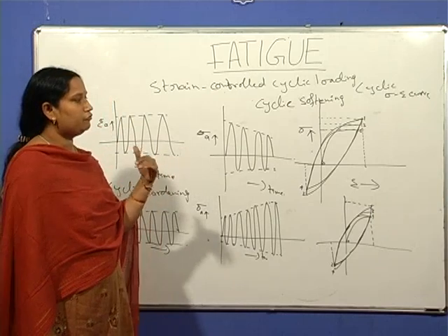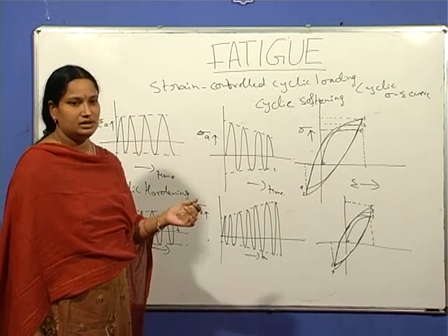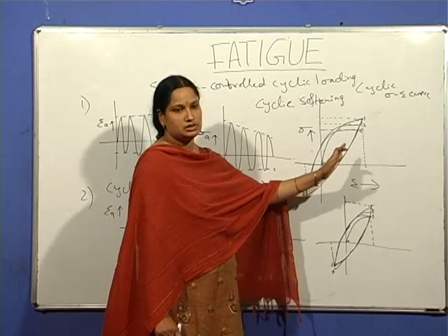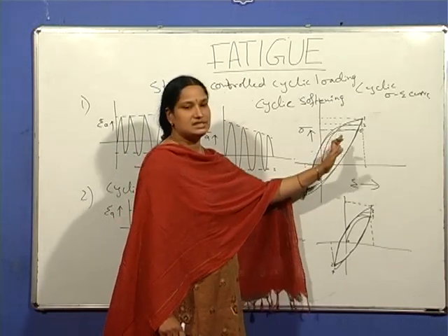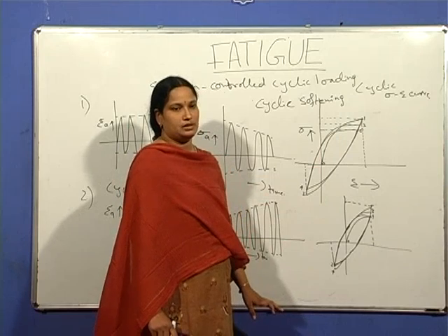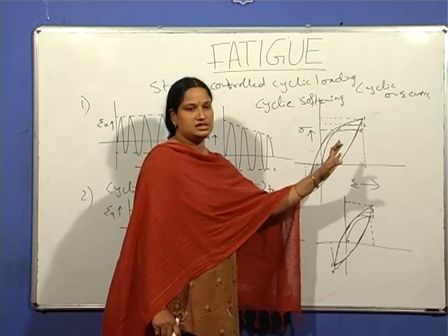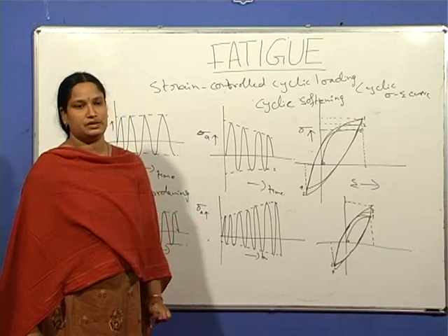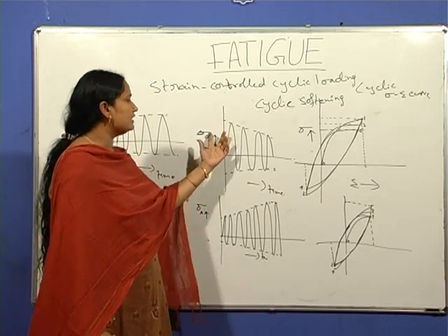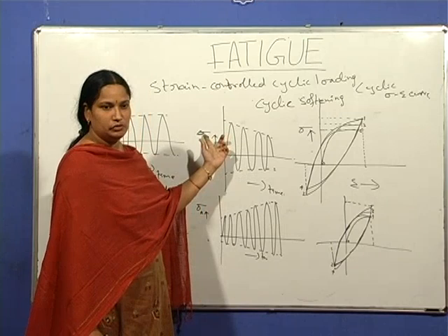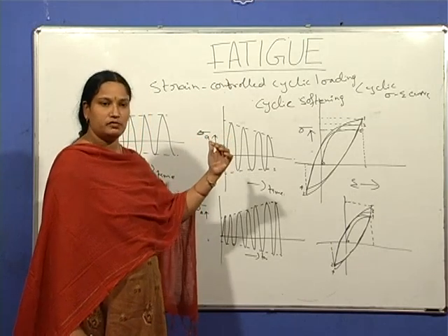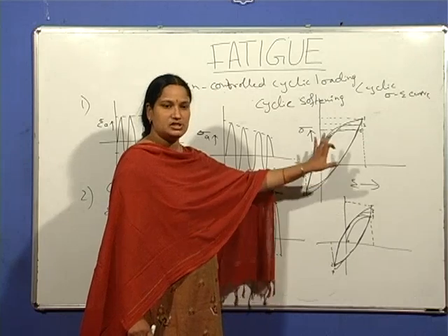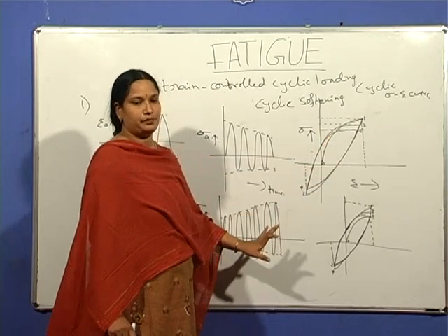After a few hundreds of cycles, this cyclic stress strain curve reaches saturation, that means it is stabilized. There is no further increase in stress amplitude.